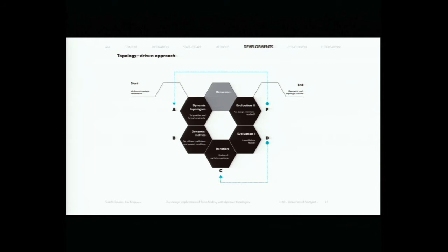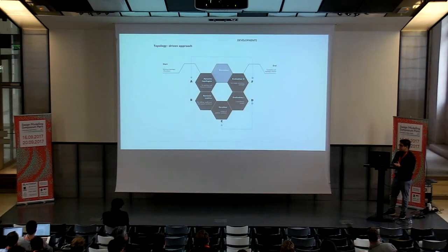The activation of topology modeling immediately breaks the linear workflow of geometric-driven approaches. So when such a characteristic is activated, we suggest categorizing form finding as topology-driven. In this case, contrary to geometric-driven approaches where form-found geometry is only variegated, in topology-driven approaches form-found geometry is also differentiated because the input model is radically different from the output model. In other words, the main driver here is topological differentiation.